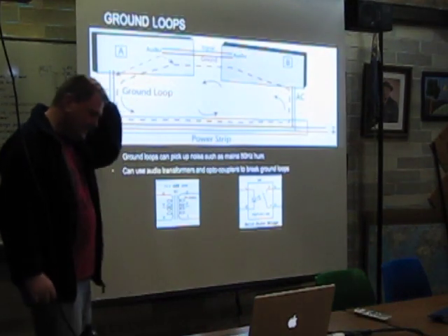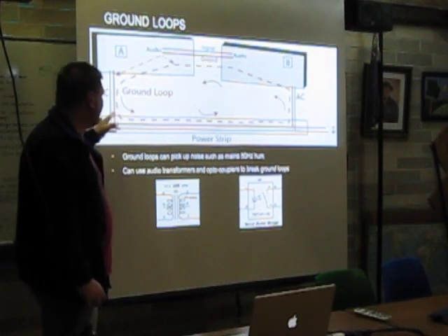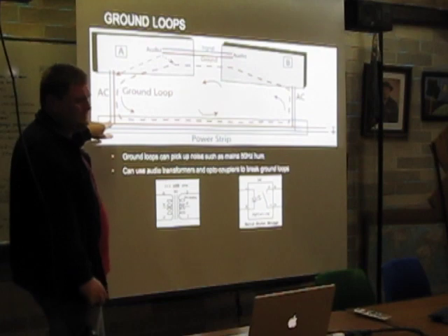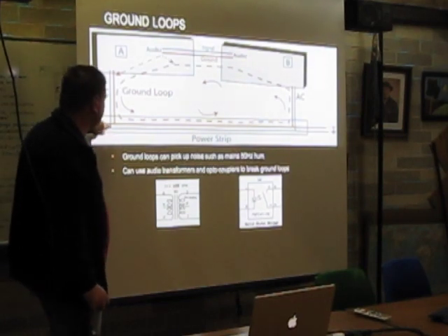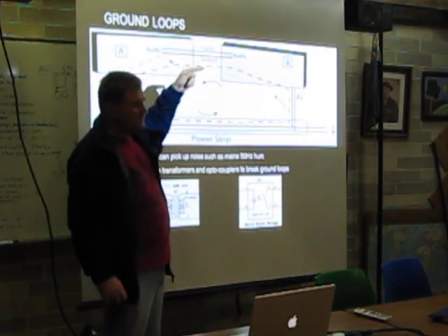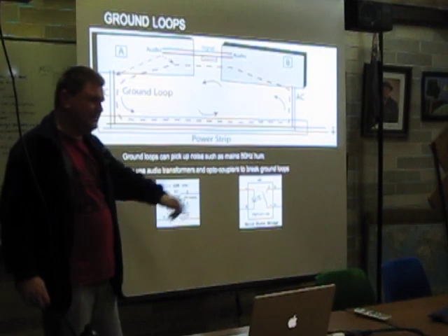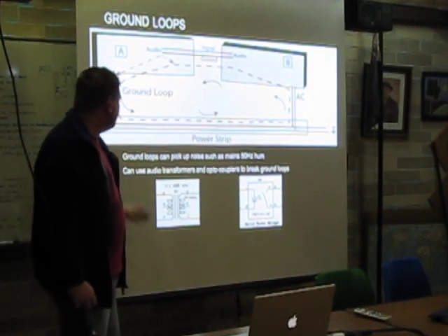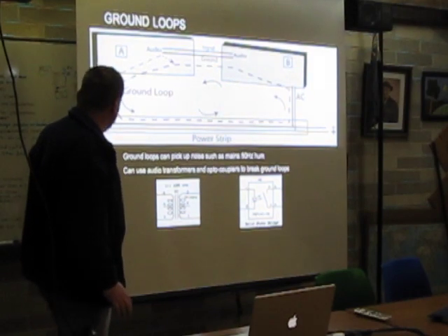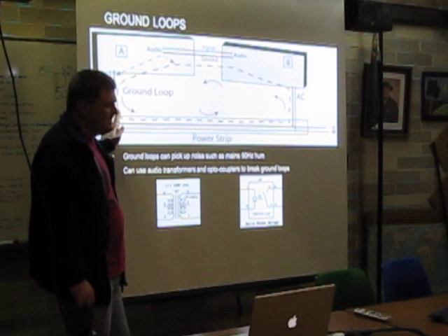One of the problems with making your own is you've got this problem with ground loops. So if you've got a computer that's plugged into, say, the AC, it's earthed, and your radio has also got a connection to earth, and maybe outside you've got an earth connection staked down into the ground to protect your antenna against lightning. So the equipment can be connected to earth in a number of different places, and between these different earths, there can be some resistance.